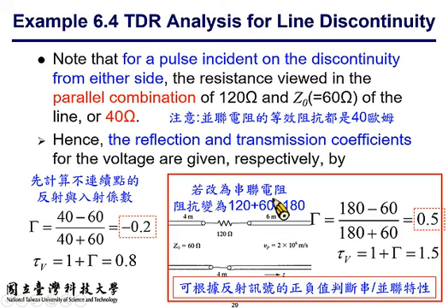The first initial step, as I already said, is to calculate the reflection coefficient at the discontinuity, and for this case you have two discontinuities. One is at the very right end, that is the short termination. And the other discontinuity is the location with the 120 ohm shunt resistor.